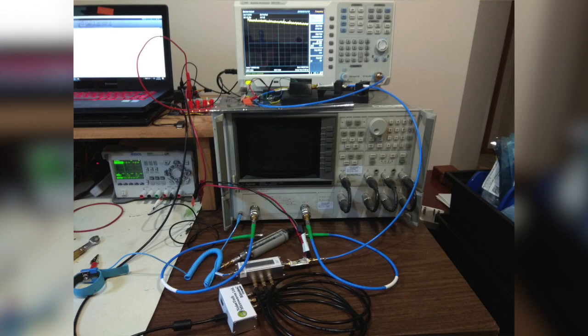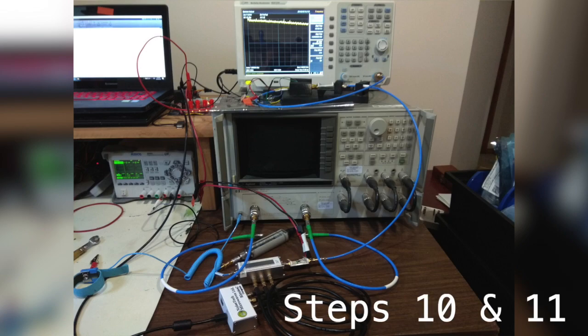There will be cold noise measurements, and you need to change the impedance generators between states A, B, C, and D, each time collecting a well-averaged trace on the spectrum analyzer. And after that, we can compute the noise parameters of the device under test by running them through the noise parameter solution script.